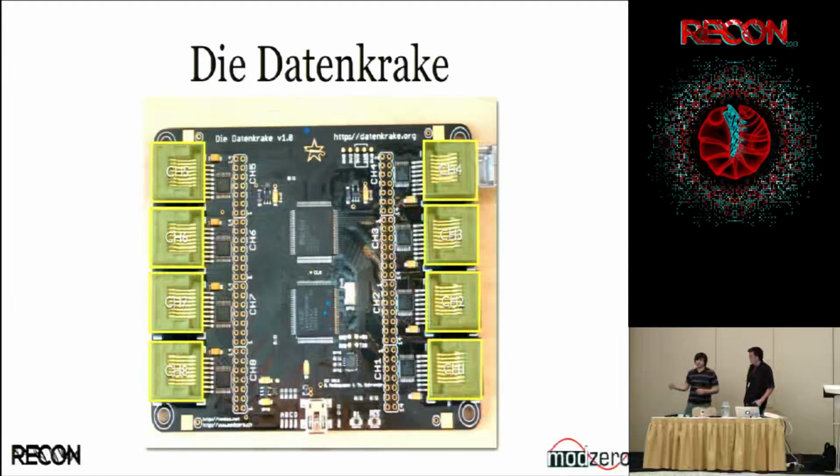There's a logical representation for each one of these channels, and you take it and replace it with something else, and now all of a sudden you're completely compatible with the rest of the project. You have your own custom logic function, so you can implement a CAN bus or whatever else you might want to implement, some crazy proprietary buses, SDR. I think we'll get into some of the examples in a bit.